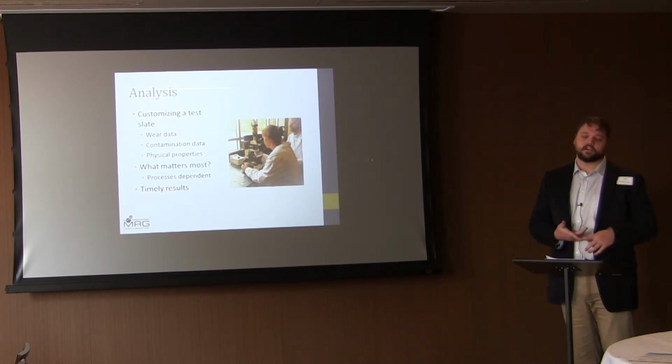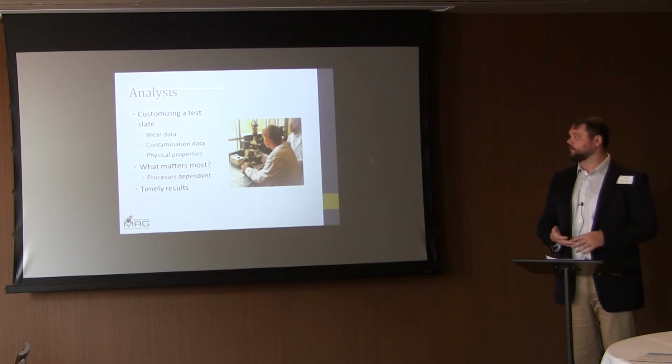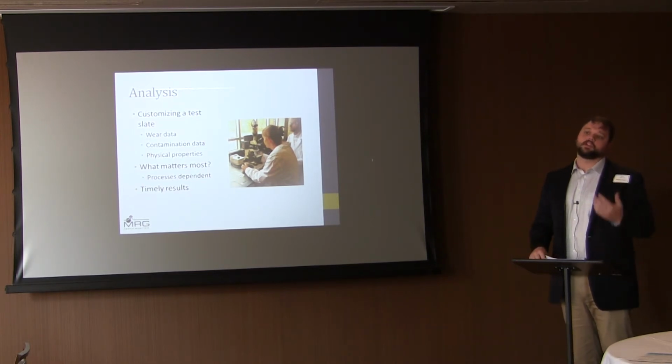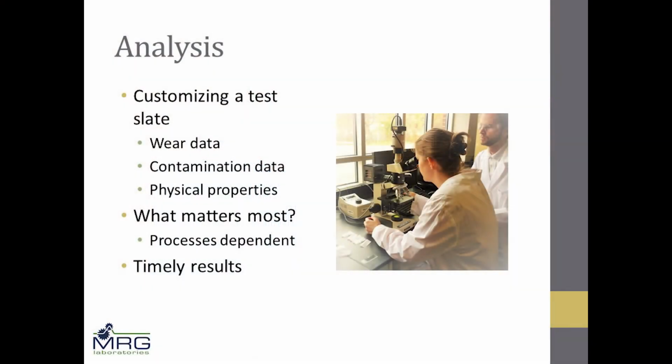And then also with grease, you have consistency. Your physical properties for your oil would be the viscosity of your oil and the antioxidants that are in your oil. Those are an important thing. A lot of people will trend those, and that's going to tell you, is your oil still standing up and preventing oxidation, or are you in a mode where oxidation is able to happen in your oil? Obviously, if your oil can oxidize, that means it's happening inside your machine. That's never a good thing.